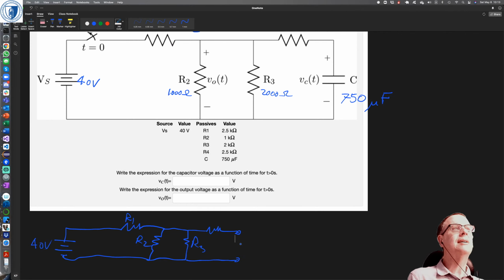The capacitor is not going to let any current flow because remember I equals C dV/dt, and dV/dt, the rate of change of the voltage across the capacitor just before that switch opens, is 0.